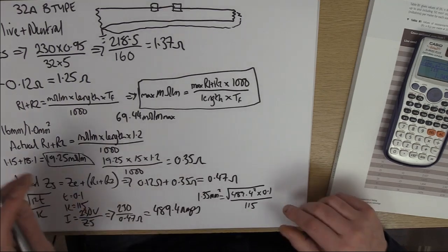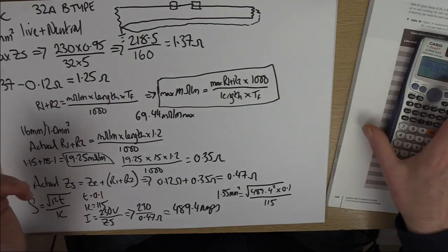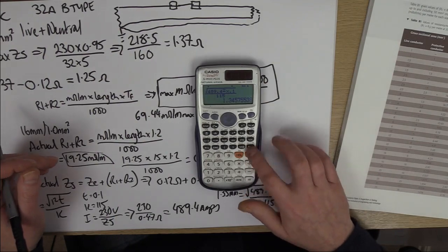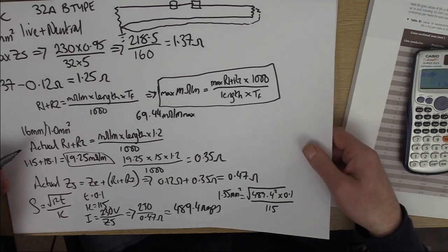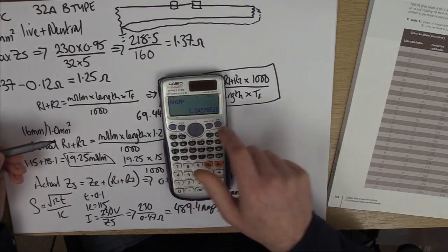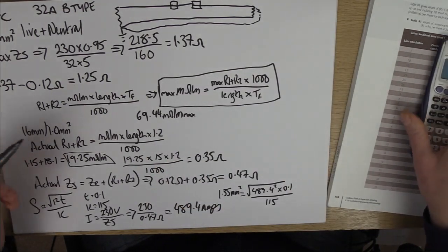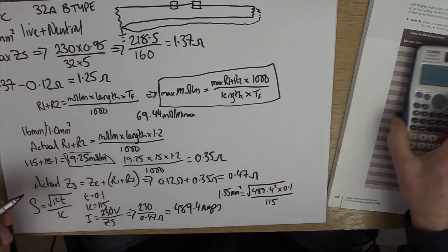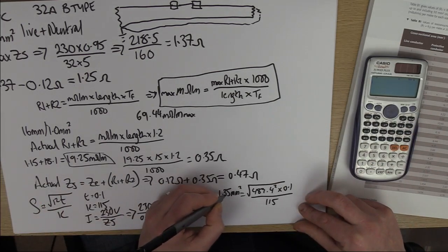And that's within acceptable tolerances because we, oh no it's not, is it? We went for a 1 mil. Oh, so it fails. Brilliant. Oh, I love it when things fail. Oh, that means we've got to go back then. So we need to choose the next size up. So we know 1.5 will work with the adiabatic at the moment, but we'd have to recalculate that ZS. So 1 mil's no good here.